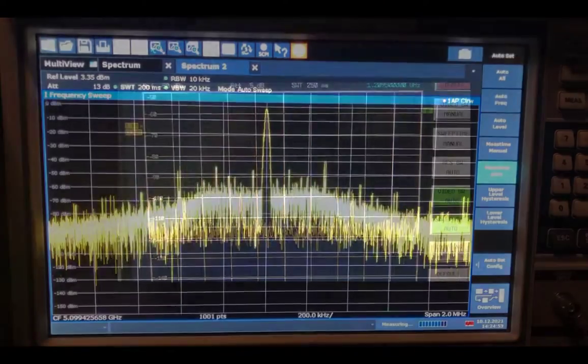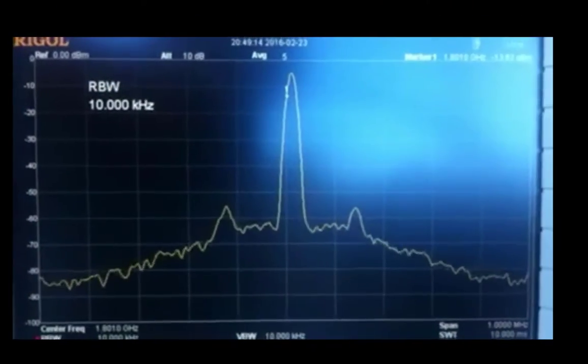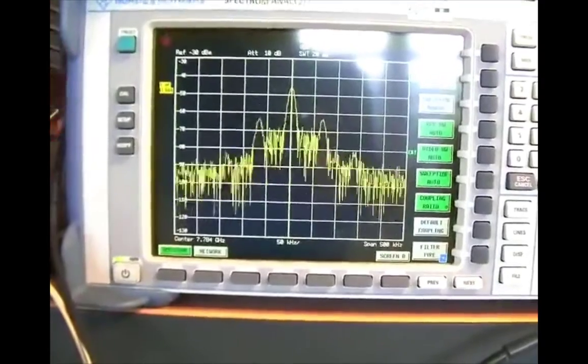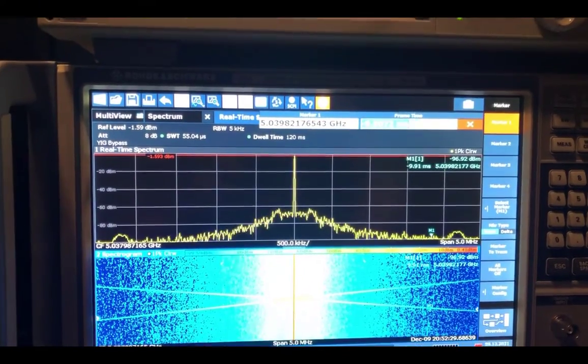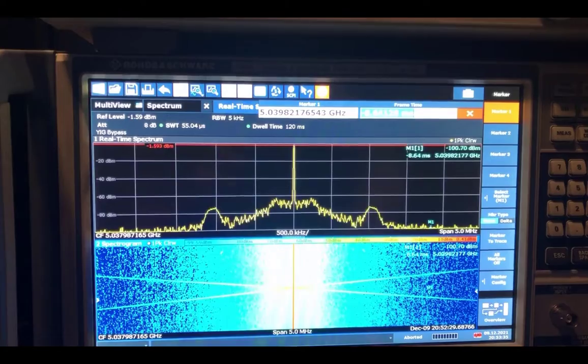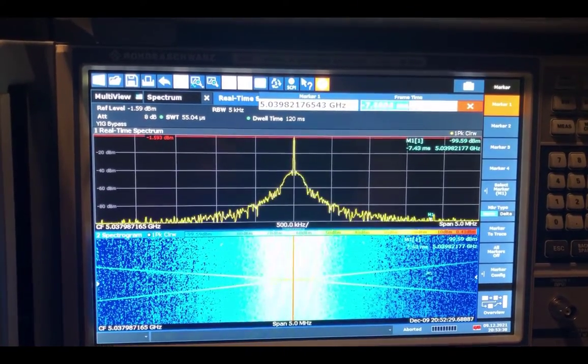The next time you see walking, marching, travelling spurs or a fluctuating noise floor, think about wandering spurs and make sure to plot a spectrogram. To learn more about wandering spurs, how they arise and how to get rid of them, see our recent publications.